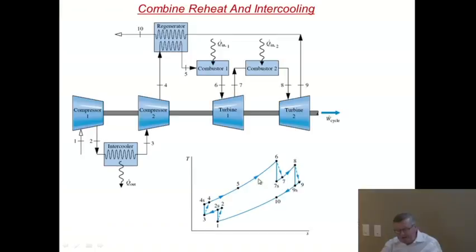Well, so what you've seen is that in your TS diagram, you have essentially added little teeth here on the hot side, which enables you to design the whole cycle with the temperature below T6. So instead of going with a sharp tooth on the top, you have a set of small teeth. And what the intercoolers do is instead of going deep down to T1, you have a set of teeth, if you want, here in the TS diagram as well at the cold side.